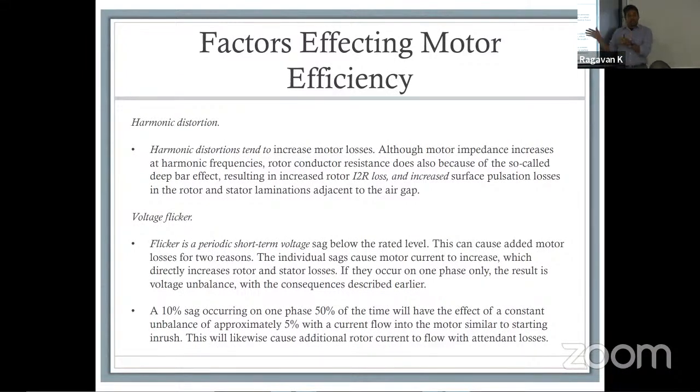A lot of times, currently what we are looking at is an IMD, an integrated motor drive, where your controller sits inside the motor. That is by definition very effective because the connection points are exactly what you have within your motor. Whatever is external to the motor at that point has no relevance because you have designed the controller to have accurate information about the length of the conductor from the converter to your winding. And now your controller is more accurate. Absolutely, you are correct. So it is something you have to take into consideration.